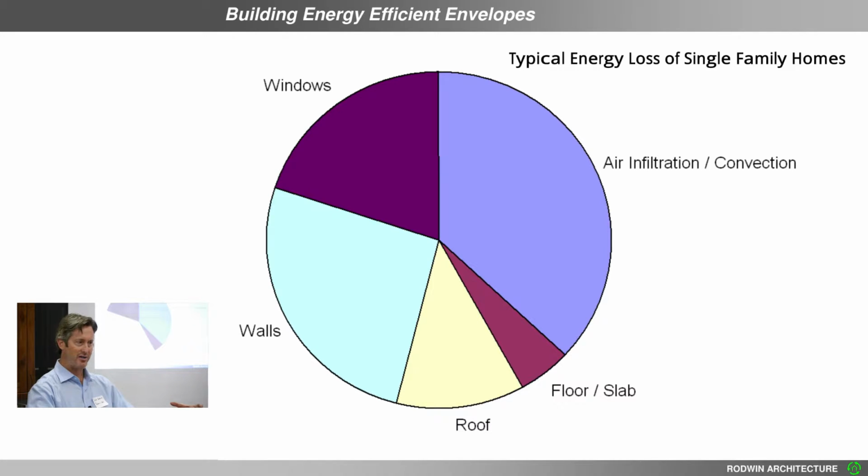But at the studs, the fiberglass is probably compressed, there are probably leaks, and equally importantly, the studs themselves are only about an R3. They conduct energy very quickly from one side to the other. So if you've ever looked at a roof on a frosty day and you see these white stripes on the roof, that's because heat is being conducted through the frame of the house.